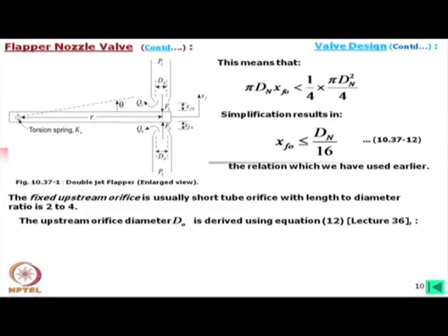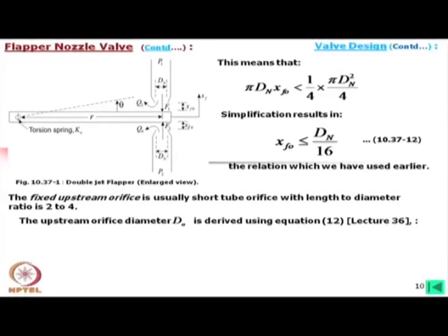But usually you find a very thin plate and a very small hole is used, and usually a straight hole, in some cases also a hole with an inclined entry or maybe on the distal side. Normally a straight hole is the best. Now, from this diameter and length ratio, we can find out the coefficient there.